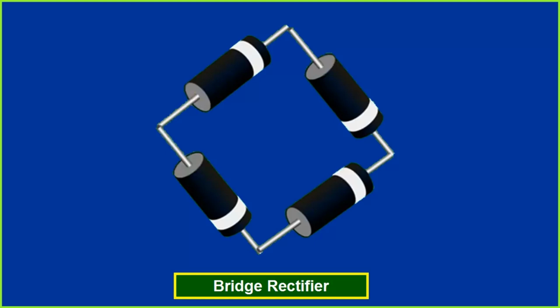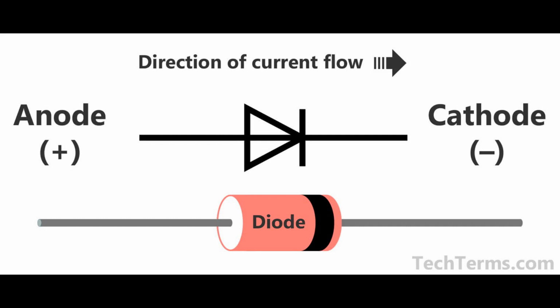The half-wave rectifier has a few disadvantages that limit its practical use in many applications. Low efficiency: since only half of the AC input voltage is used in the output, the efficiency of the half-wave rectifier is relatively low. Pulsating output: the output of the half-wave rectifier is not smooth, which can be problematic in some electronic applications. Additional filtering is required to obtain a more stable DC voltage.